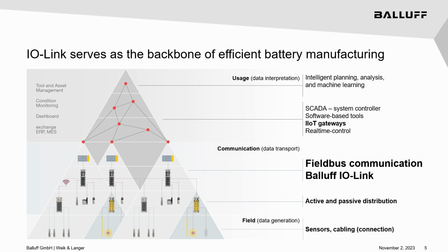We also talked in one of the last sessions about the ability to increase the set of information in a sensor or in a device, which we already had years ago. But the question was always how to get this information out of the device and transport it to the position or to the PLC where it's needed, or maybe to a higher level. And this ability we now have with IO-Link.